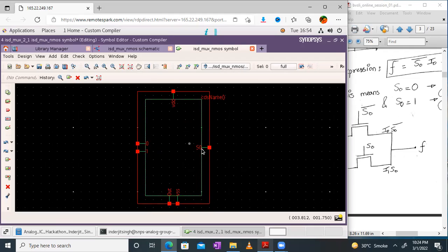Here it is. So here I will have a select pin S0. Your VDD will come, output will also come over here. So let me select this S0 pin here only. I will click on this, move this pin away and keep it over here. Output pin, I have to add it over here, so inputs over here, output over here. So again, I'll select this move option to select this pin and bring it over here. And then I'll orient this VSS so that it's aligned with VDD. I'll slightly move towards the center. Yeah, that is fine now.